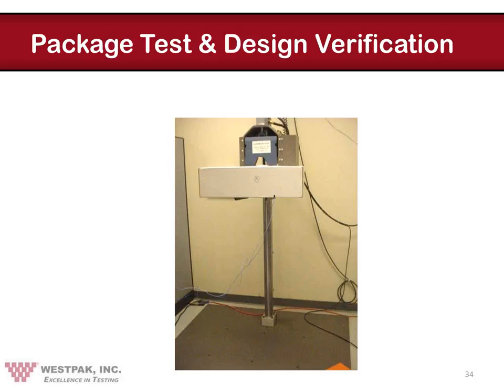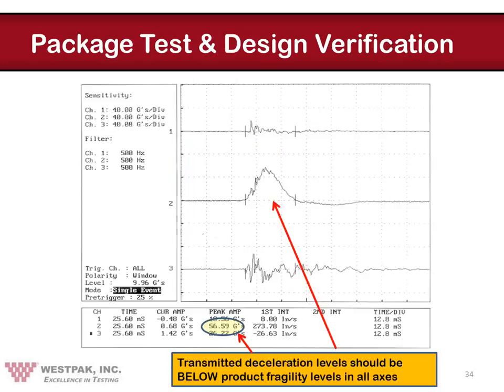Testing is normally done on a drop tester because we want to guarantee a flat impact, which these machines are designed to do, and we want a rigid impact surface, and again, these machines are designed for that. So it's important that the machine be guaranteed to deliver this flat impact all the time. That's why we use them.